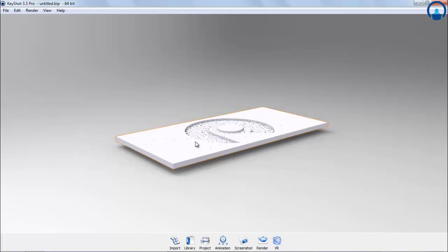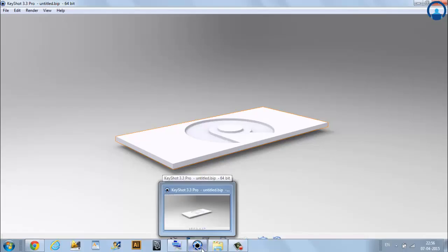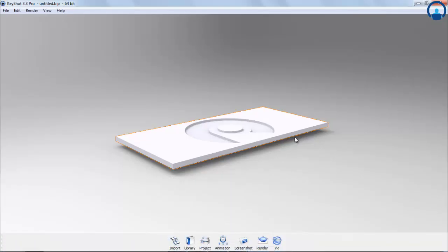To embed your Keyshot VR, simply use one simple HTML code anywhere you can embed an HTML snippet. Copy the address from the address bar and then paste the URL into the source attribute of the iframe tag. In the same tag, you can also adjust the width and height of the VR to fit the size of the embedded area.